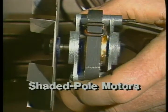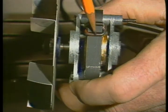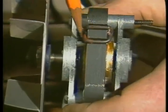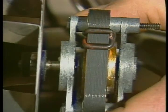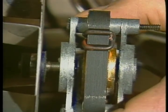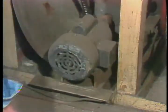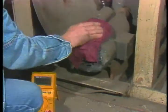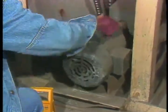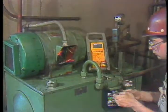Small light-duty AC motors use a shading coil to provide startup torque. A shading coil is simply a shorted turn or two of heavy wire around a part of the stator core. Startup torque and efficiency are both quite low. Even the best single-phase induction motors are generally less efficient and more likely to give problems than three-phase induction motors. When three-phase power is available, it nearly always makes good sense to use a three-phase motor.